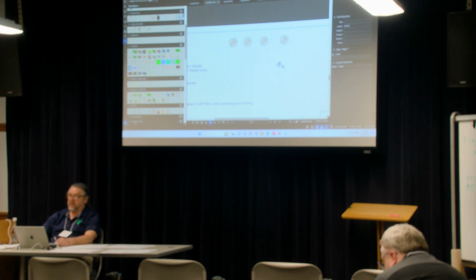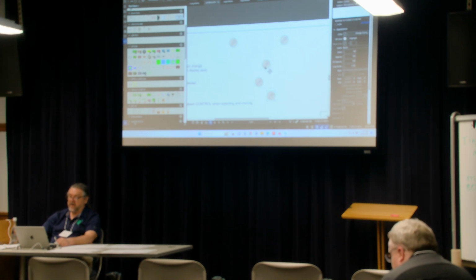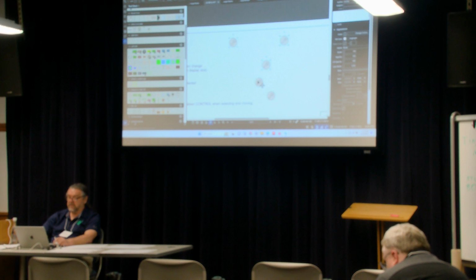The way that Bluebeam decides which one is your reference is the first one that you click. So let's say I want everything by left edge on this microphone. I click it and then start selecting the others. And then align to left edge. And there it is. And let's say I want those evenly distributed up and down. There's a command for that. Now they're evenly distributed.